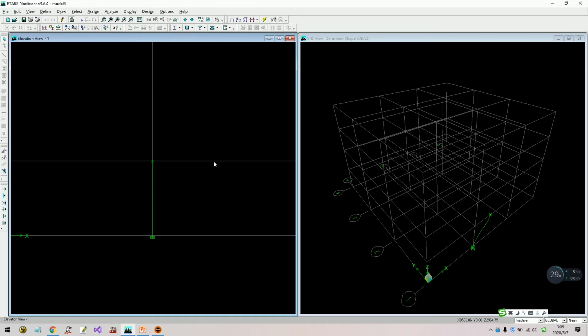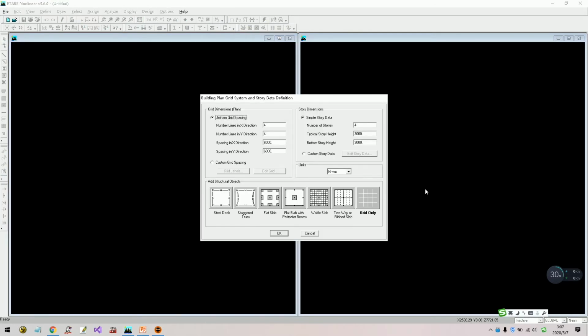The second part will build the 2D and the 3D, or even the 3D structure. I think most of you will consider how to build a 3D structure and compute the time history analysis for this one. Okay, I will start the 3D model in the Etabs platform to build a several-story frame structure in Etabs, and run the spectrum analysis, time history analysis, and modal analysis in these 3 parts. Just to show you how to operate this software.